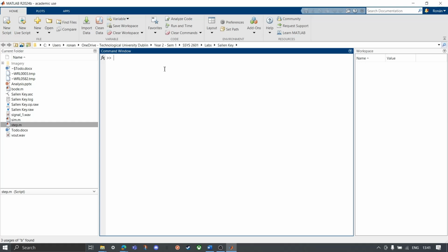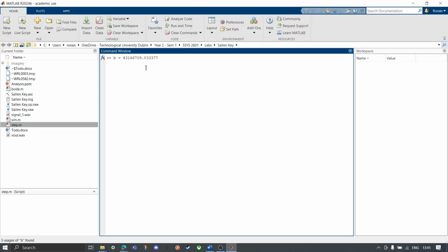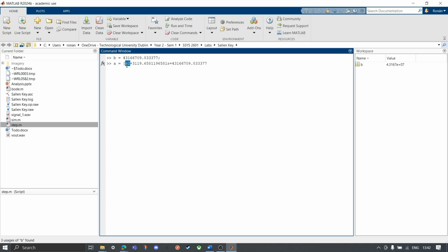There is another way to get the step response, and that's using MATLAB. So if we use B and A coefficients, we can get from the transfer function. We can do it in MATLAB. So here in the calculator, we can just copy these values. There's our B, then our A is going to be like this. So if we just copy them, that'll be 1, and then that there, just like that. So now we want to make, so it says this one's equal to the transfer function of B, A, just like that.